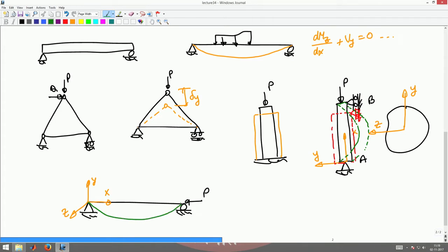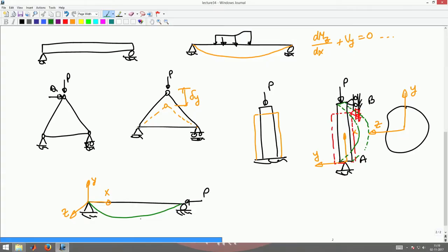like this is possible. If the deformation is of this form, is it possible? To answer that, what should happen? There should be a smooth displacement field from which you get the strain, then it has to satisfy the constitutive relation to find the stress, and then you have to satisfy the equilibrium equations. If it deforms like that, it's like a beam bending problem.